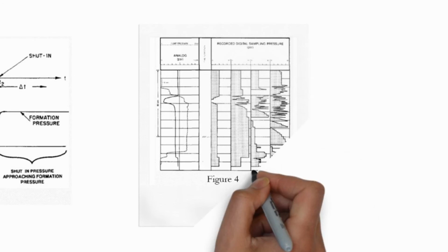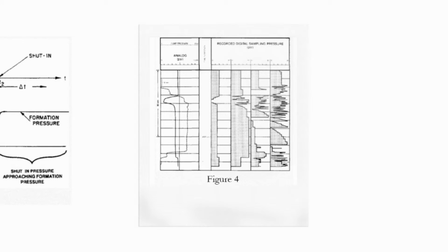We move to the next figure. Figure 4 is a typical log recorded by a formation tester that has a single pre-test chamber. In the left log track, the solid curve represents the pressure detected by the gauge within the tool sampling system. Time is increasing downward along the log. The hydrostatic mud column, drawdown and formation pressure are clearly detectable. The sudden increase at about 105 seconds corresponds to the tool retraction and opening of the equalizing valve.